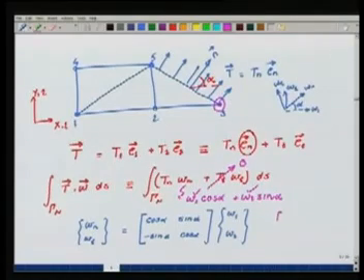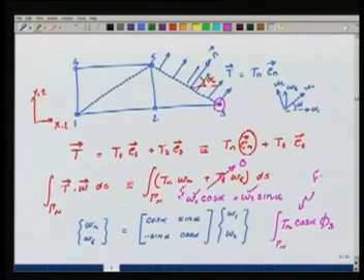It will be the integral over this edge, Tn into cos alpha, phi 3. This will go into equation F5, right? It will go to the x component of the load vector. Similarly, the other one will have Tn sin alpha phi 3, which will go to F6.